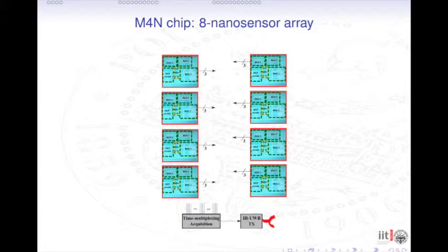All these signals, since they are quasi-digital signals, so more or less square wave, can be easily transmitted, and they are really compliant with the impulse radio ultra-wideband technology. In fact, the transmitter generates a pulse at 3.3 or 4 gigahertz in correspondence of a rising edge of the quasi-digital signal.